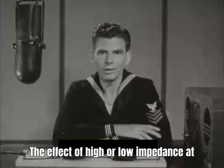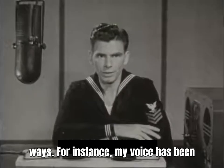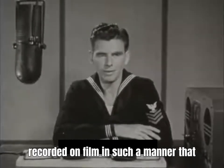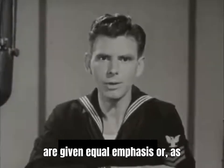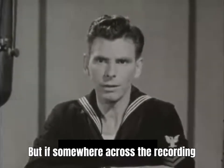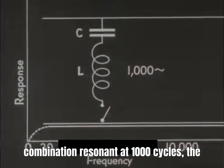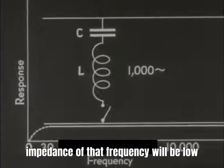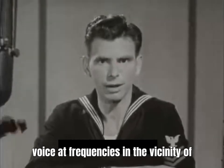The effect of high or low impedance at resonance may be illustrated in many ways. For instance, my voice has been recorded on film in such a manner that all frequencies from 30 to 10,000 cycles are given equal emphasis, or, as it is commonly expressed, response. But if somewhere across the recording circuit there is inserted a series L and C combination, resonant at 1,000 cycles, the impedance at that frequency will be low enough to partially short-circuit my voice at frequencies in the vicinity of 1,000 cycles.